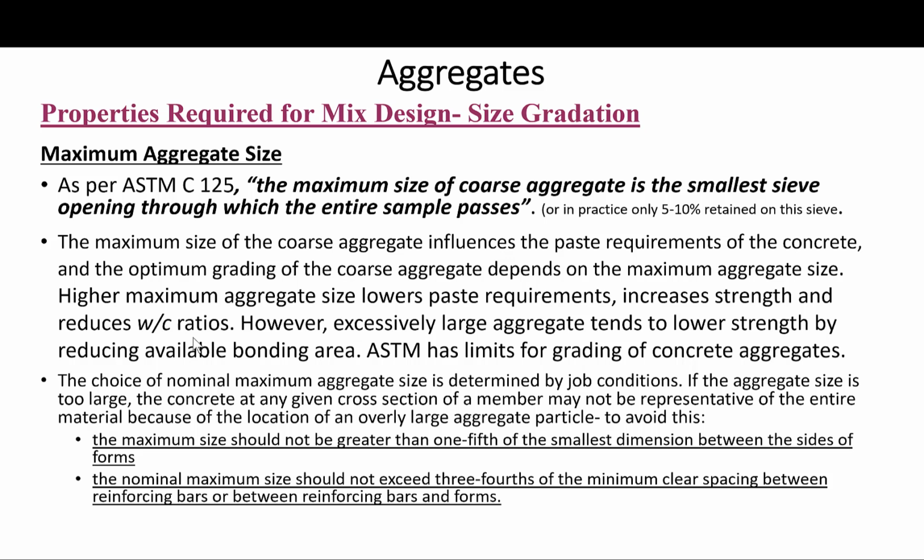Okay, but most equipment for testing concrete is designed to handle only up to 37.5 millimeter aggregates. So the maximum size aggregate of this range, 37.5, as you probably will notice. Larger sizes must be screened out before testing, and you have something to be aware of. Most jobs you will work on, other than unreinforced mass concrete, you will not see more than this maximum, 37.5 millimeter aggregates.